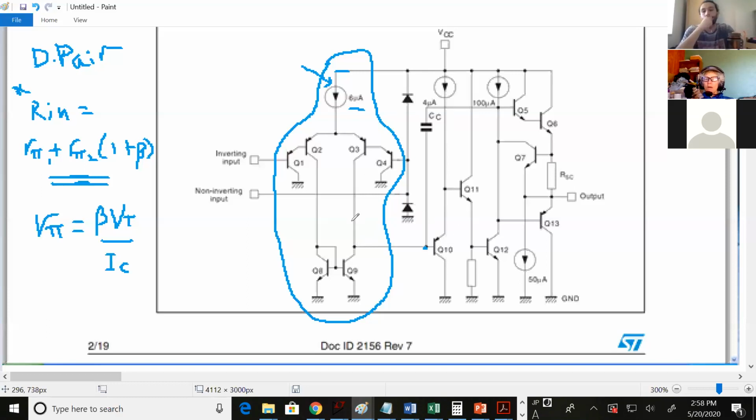So this probably, I can almost guarantee that this was being loaded by your gain stage. So they needed to protect it. And part of the reason it was so easy to load probably was because there's so little current going through here that even if a little bit gets stolen, then it just messes up the diff pair.